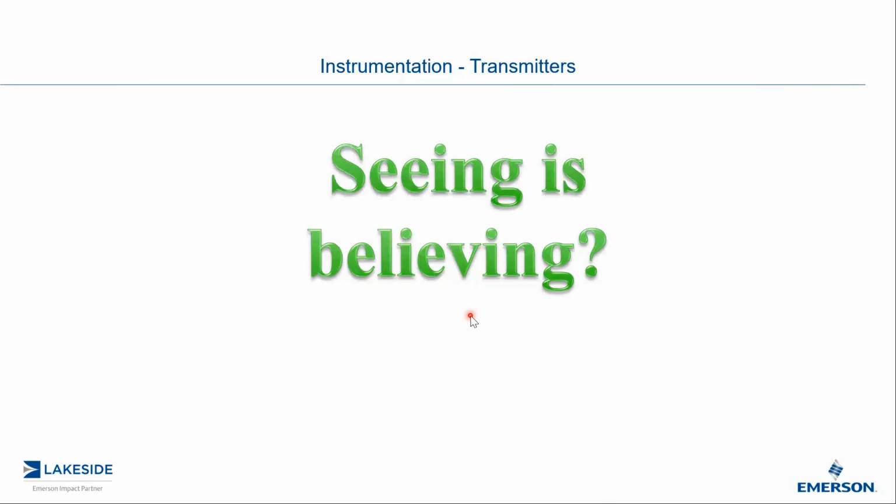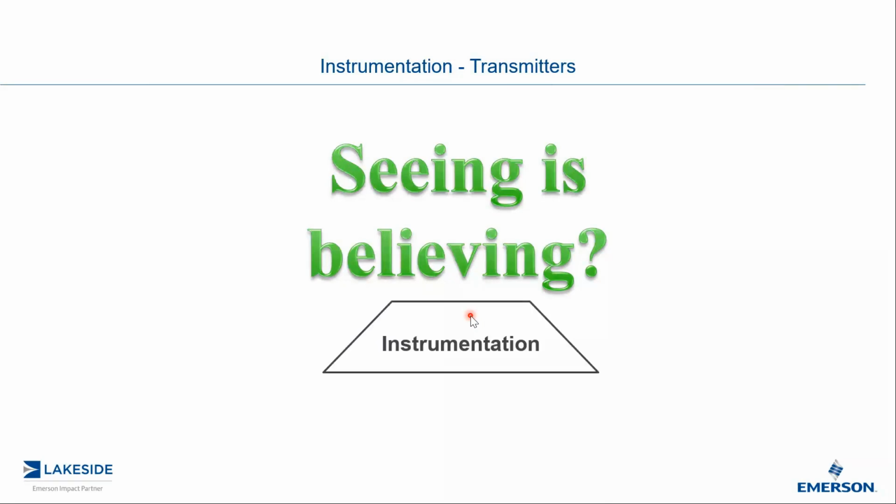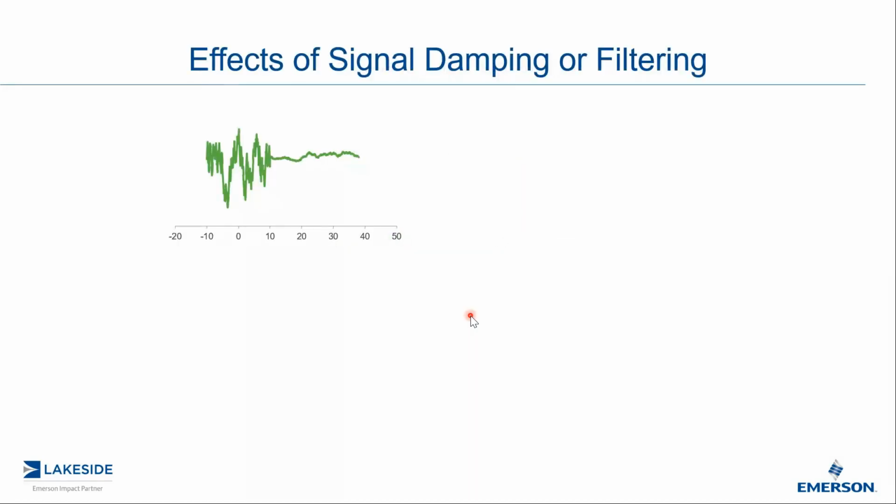Instrumentation, seeing is believing. So let's look at it from two points of view here. A lot of times I have the Lakeside tuning index that I've developed, and we'll talk about this a little bit later on, but I also look at excessive PV filtering in all the PID blocks.